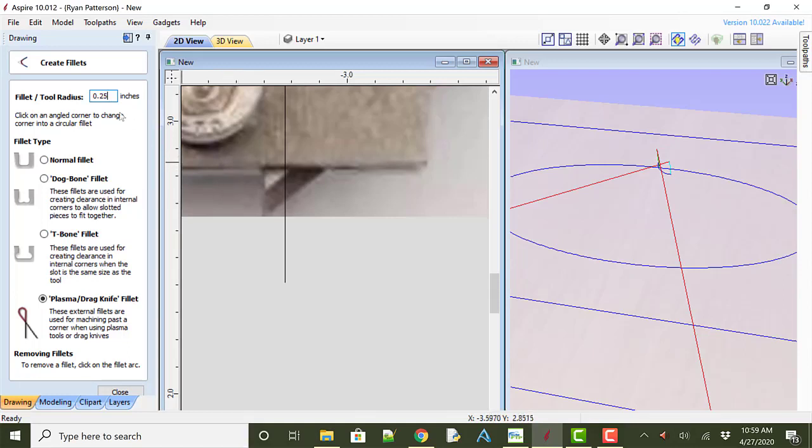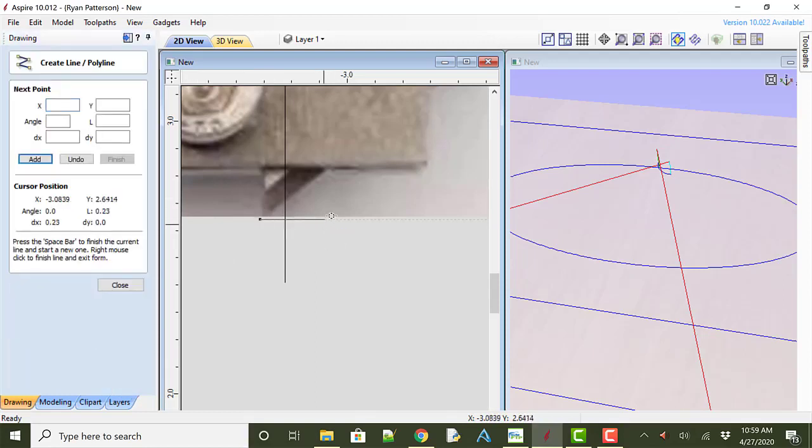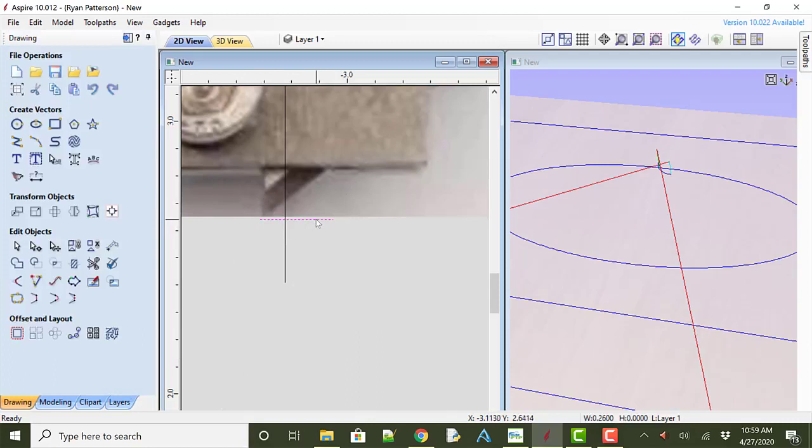The reason we have to pay attention to this is, imagine we are cutting full depth, from the bottom tip of this knife to the top of the total depth here. Now we have a total width that we're cutting from the leading edge of the knife on top versus the back edge.